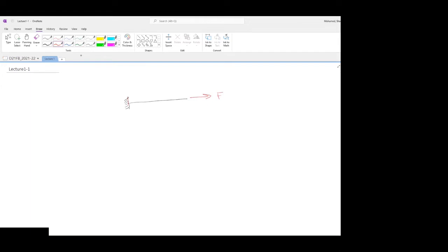You have the load to be F and the cross-section to be A. The stress in this case is going to be F over A. Now, this is something quite simple, and you would all agree on that. Now, the stress is the number you are going to use for the design. So eventually you design your beam so that this sigma should not exceed sigma y, which is the yield.